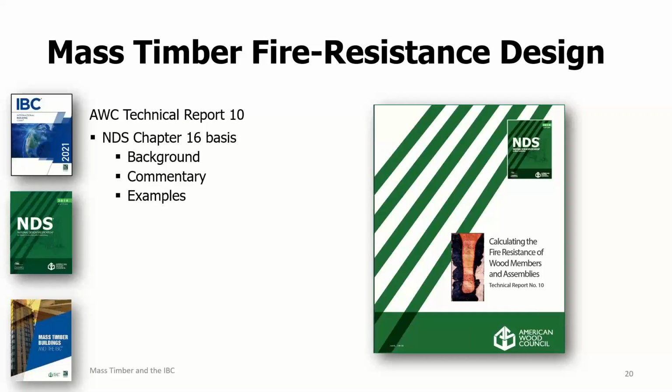These provisions for design of fire protection, both combustible protection and non-combustible protection, allow for designs that go beyond the 2-hour fire resistance rating limit that I just mentioned on the last slide, because that 2-hour limit is applicable to the exposed wood members. So any additional fire resistance gained from non-combustible protection applied over that can go beyond that 2-hour limit.